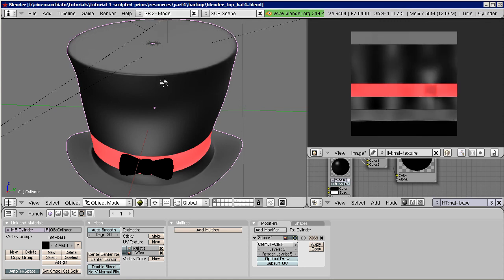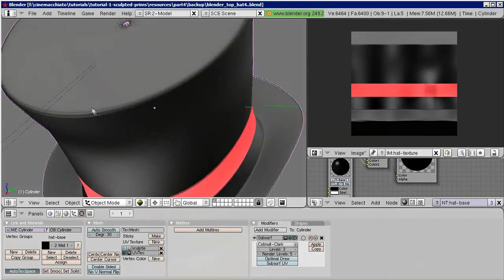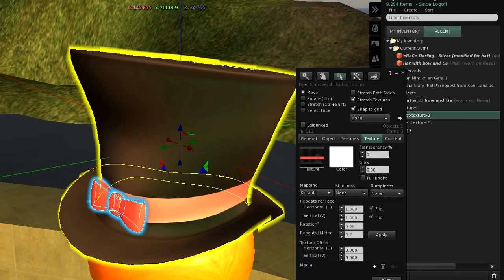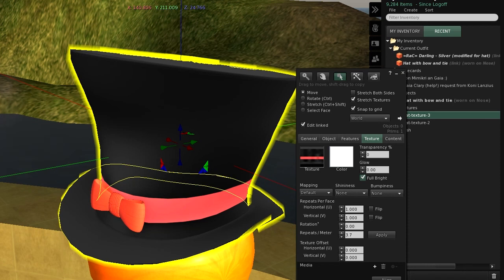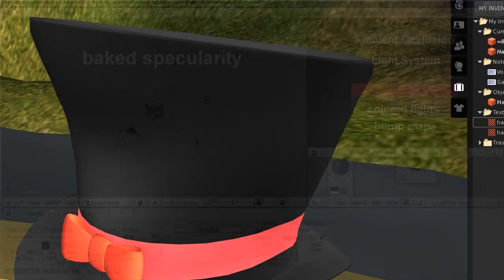After baking, all the fine details are visible in the texture, and so you can get very fine details without increasing the mesh face count by just baking them into the texture, and using this texture on your low poly model. Now play around with the lights and see how your specular effect changes with the light settings. For example, you could get a bit adventurous and colorize your lights.